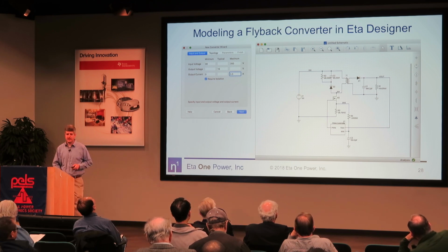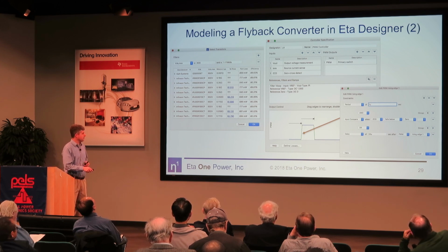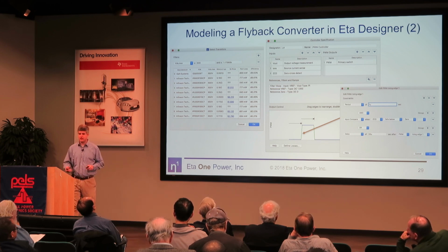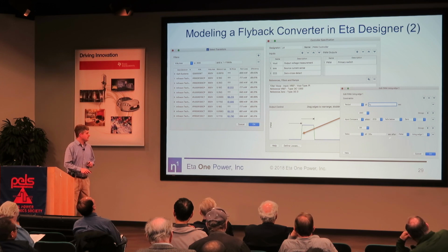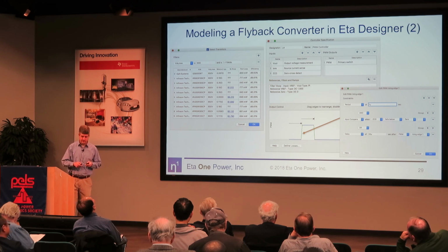So we're actually going to modify it to be a valley switched mode, which I won't get into the details, but anyway, we can specify the control here. We can put constraints on the edge. So for example, here we limited the period or the switching frequency between 50 kilohertz and 140 kilohertz. And we actually switch when you get a valley in the voltage waveform, which improves your efficiency.